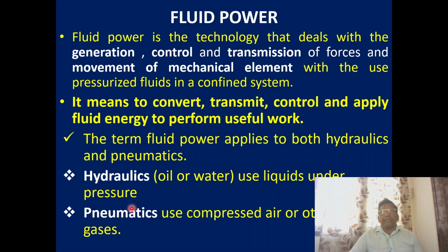We are always calling this fluid power. What does it mean? It's a technology that deals with the generation, control, and transmission of force to do something useful. For doing the useful work, we have a mechanical element. It takes up pressurized fluid in a confined system. So it's a technology that deals with the generation, control, and transmission of forces and movement of mechanical elements with the use of pressurized fluids in a confined system.